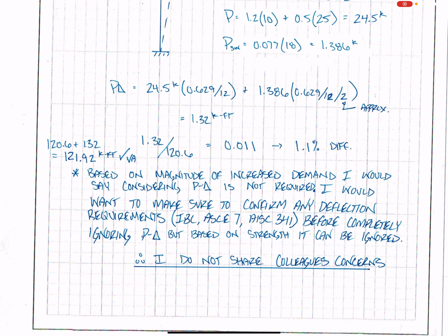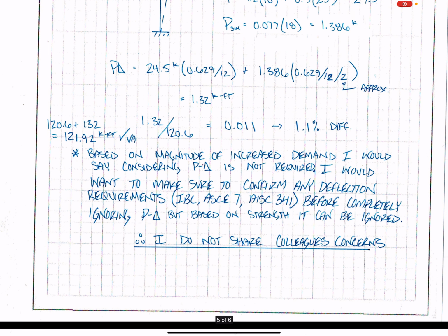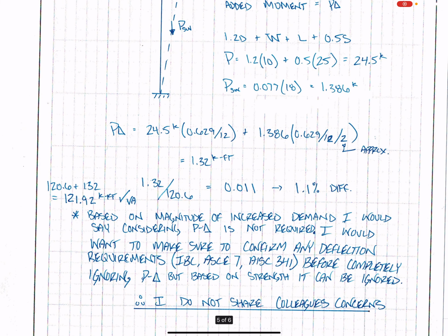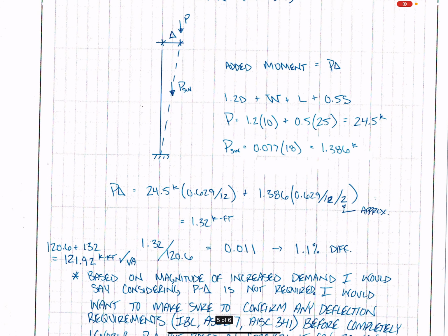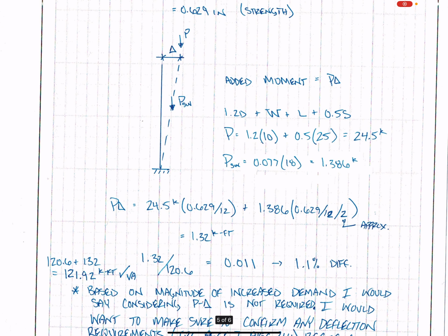But I really said, okay, if John came to you and said, man, I'm really freaked out about this P delta analysis on this column, I want you to say, well, John's probably overreacting, right? Or Elias is overreacting, okay? For that deflection at the middle where you applied self-weight, I just assumed it was a straight line, you just halved it, just to make sure that it was somewhat incorporated so that I would get somewhat closer.